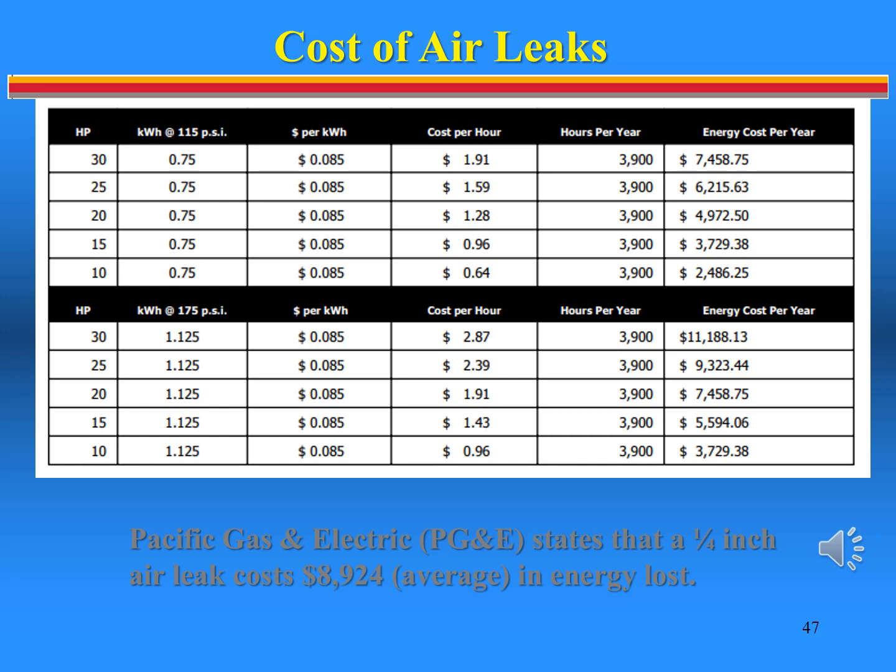One of the most common leak points in plants is at abandoned equipment. Consider adding an automated shutoff valve in the supply air line, which closes when the machine is turned off. Two methods of detecting leaks and equipment used to detect them are ultrasonic and acoustic detectors. Ultrasonic leak detection is the best way to find leaks in your air compressor system. An acoustic detector can recognize high-frequency air turbulence associated with leaks.